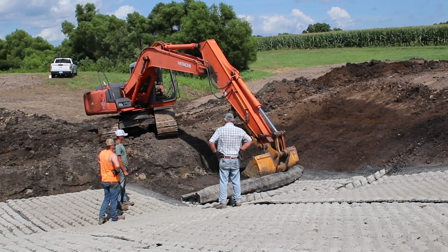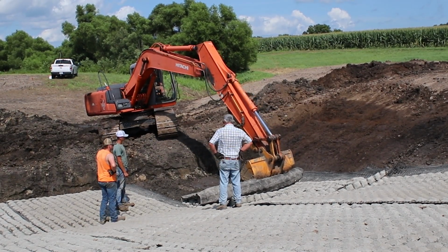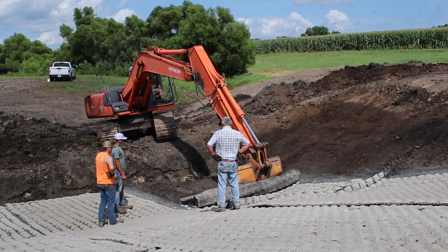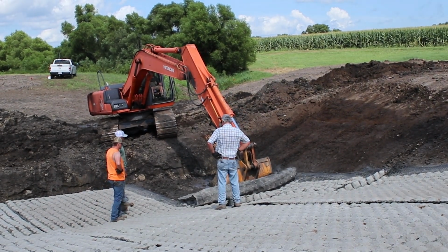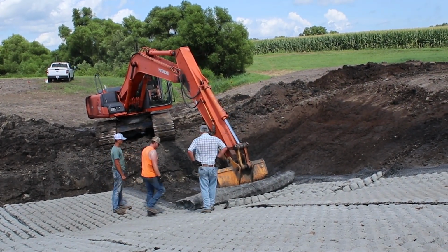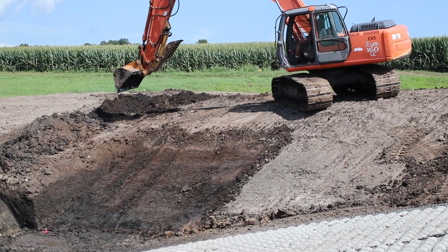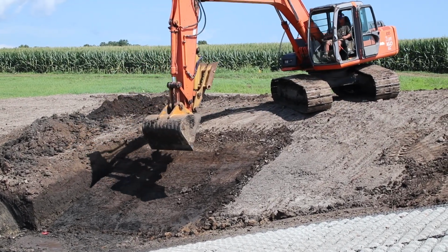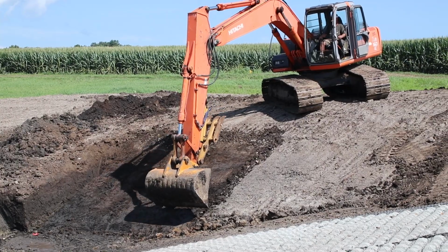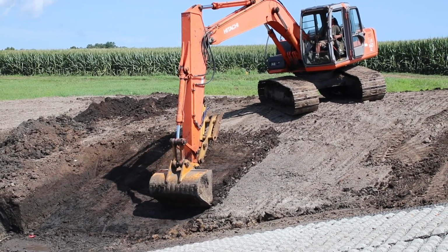The mat didn't always roll down the slope exactly in the position the contractor wanted. Here the excavator is nudging the roll over so it overlaps the 12-inch geotextile geogrid extension. The last roll to go in went in on the southern side slope. The side slopes can be more challenging than the flat portions of the chute to unroll the mat.